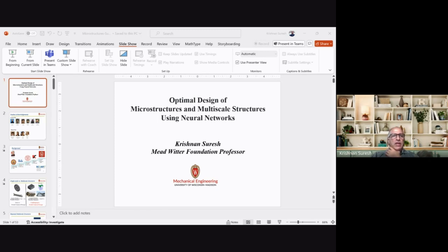So let me explain in a very simple two-dimensional setting. I have a simple structure, which is fixed at the left and has a load applied at the right, hopefully very easy to visualize. And I have some kind of a repeated multi-scale. So I have these little tiny structures that repeat themselves in one or more regions. And this is an example of two microstructures. What I want to do is account for these fine features, just like you saw in the Eiffel Tower. I want to account for these fine structures, but I want to predict the global behavior.